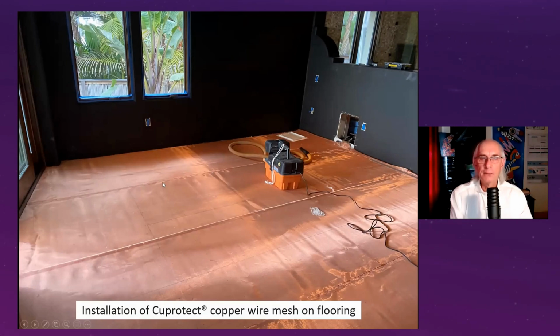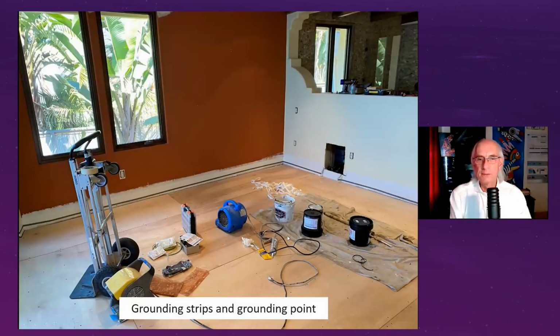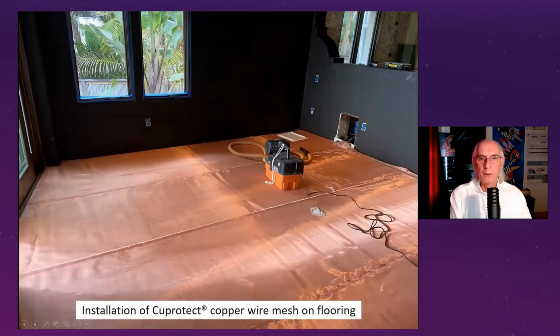Why do I use a copper wire mesh? Rather, why do I not paint the floor surfaces? For a very simple reason. If you look at it here, we got seams here in the wood, and the building is going to move and shake, and paint may crack or deteriorate, while a copper wire mesh is fairly flexible and it's going to endure movements and not be destroyed or torn. So that's why we use a wire mesh.